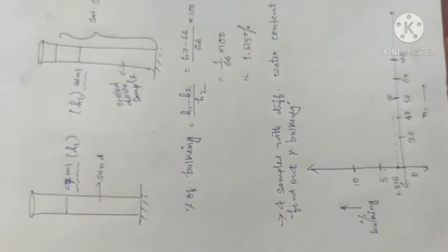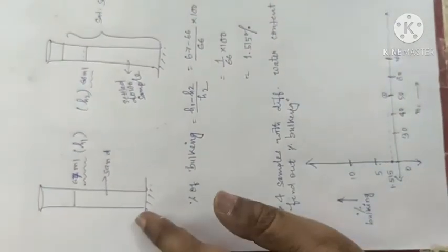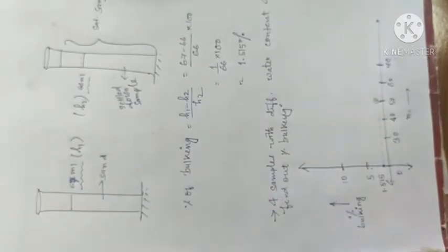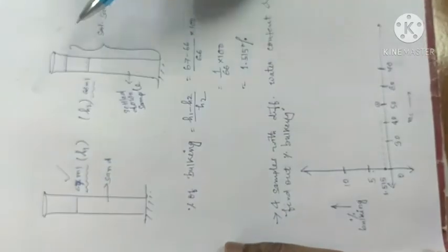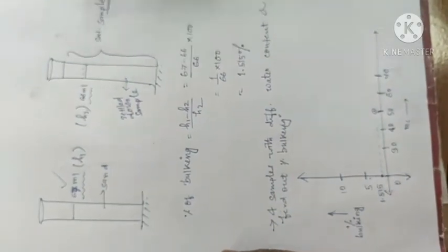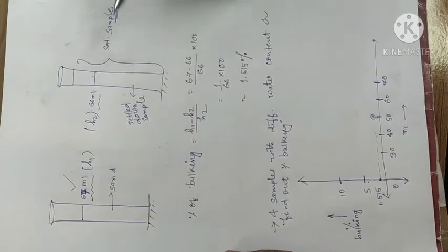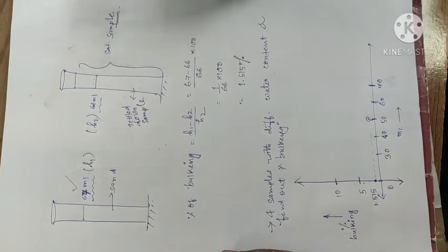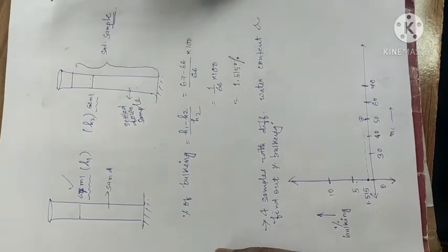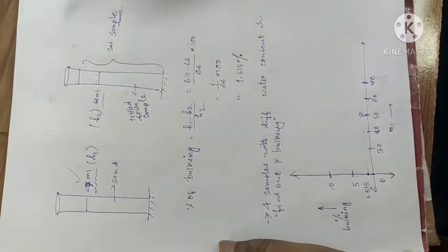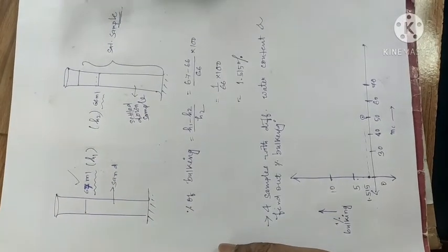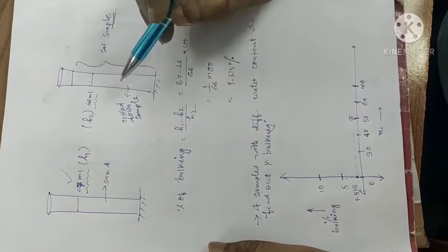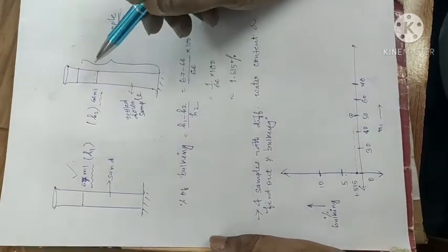So now we will go for our calculation part. Now you can see this is our cylinder with sand. We filled the cylinder with 2/3 of the sample, that is 67 ml. Now, in our step 2, first we put 50 ml of water, that is half of the capacity of the cylinder. Then we put the sand sample in two phases, half and half. Then finally we stir it, and we found the height of the settled sample is 66 ml, that is our S2.